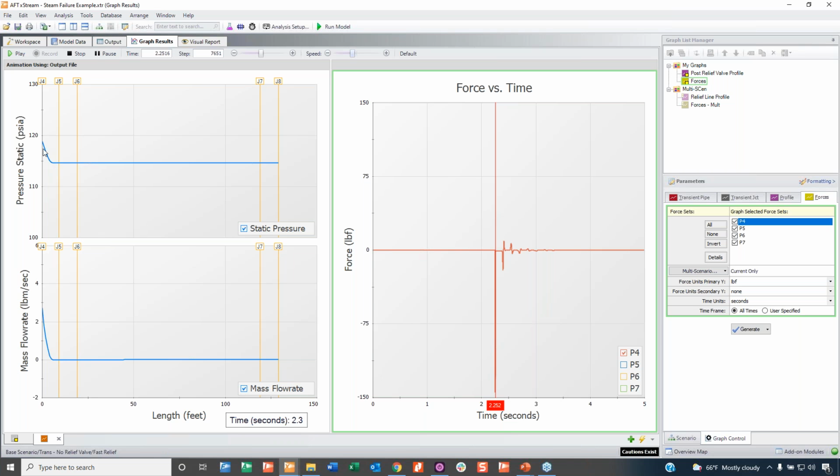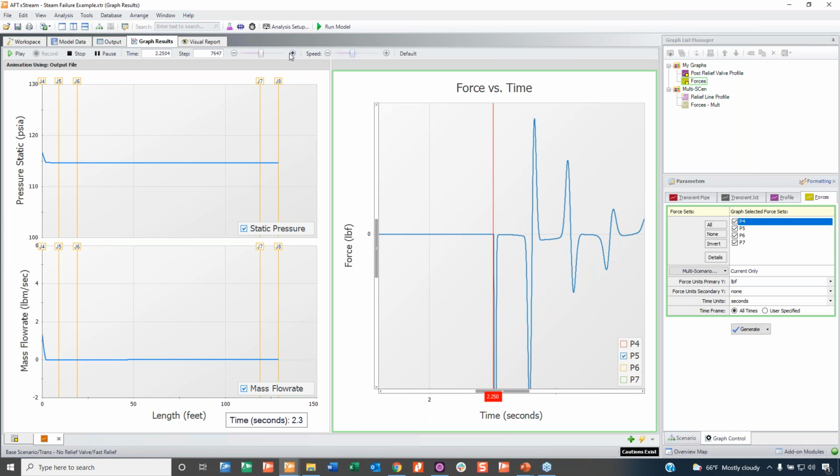So because that wavefront is so steep, the inlet and outlet see such a difference, right? And then the wave, what you'll see is the wave comes back and comes back through, and then you see the second spikes that are much smaller. Frictional effects have dampened out the wave. So now if we moved into pipe 5, well, our wave's already there. So similarly, right, we're at 0, and then my wave comes through, and yep, the end of that pipe, now a new pipe, hasn't seen the pressure rise, but the beginning starts to, right?